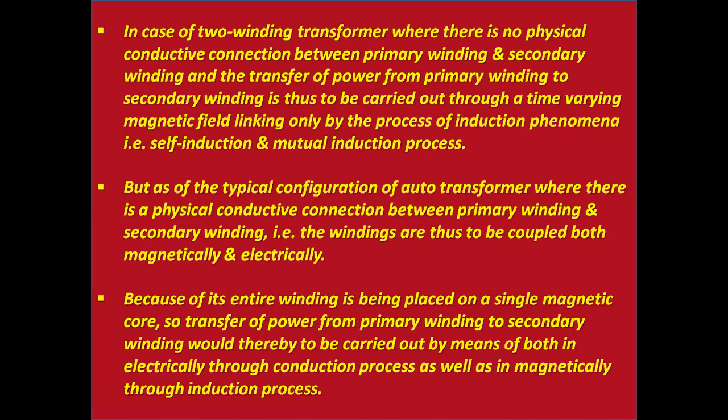In the case of a two winding transformer, there is no physical conductive connection between the primary winding and the secondary winding, and the transfer of power from primary to secondary is carried out through a time varying magnetic field linking only by the process of induction phenomena, that is, self induction and mutual induction process, for conventional type two winding transformers.